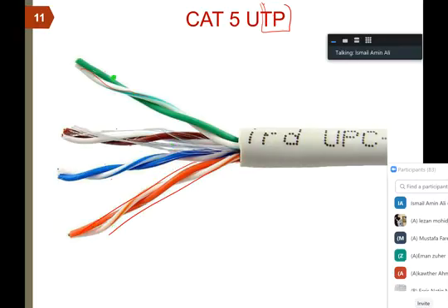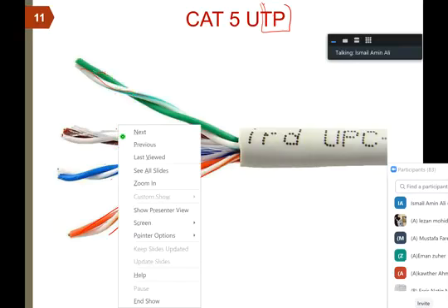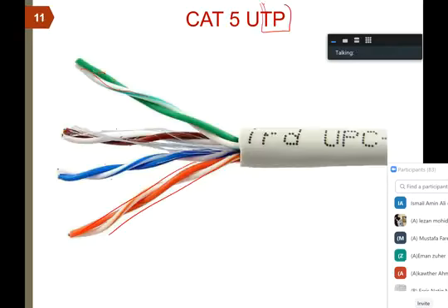So you have always the pair, which is the color, and the other cable is white with that color stripe. So here is brown and it's white with brown stripe. Okay, it's blue, and white with a blue stripe. So you know it's a pair. If you connect this side, you know how to connect the other side, because if they are not color coded, you'll not know how to correctly connect them.